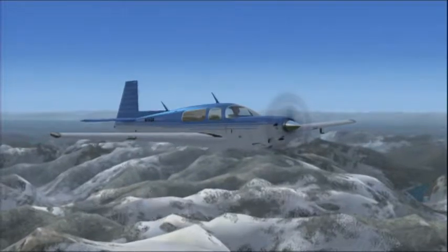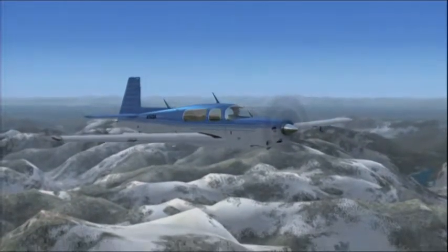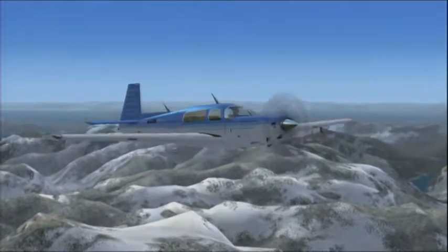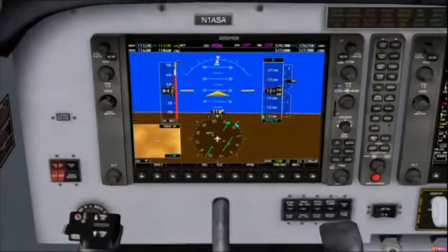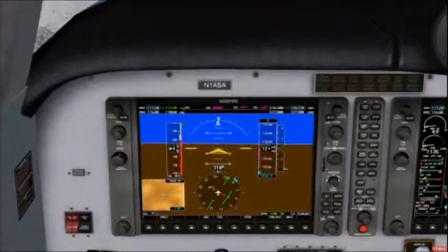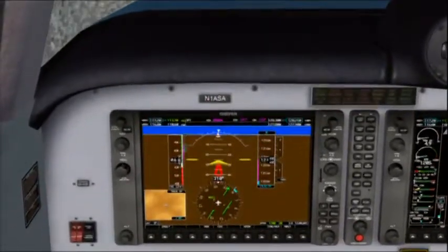And this makes sense because with fewer air molecules, you need to fly at a greater angle of attack to generate the same amount of lift that you would generate at a lower altitude. Therefore, the wing will reach the critical angle of attack at a higher airspeed.